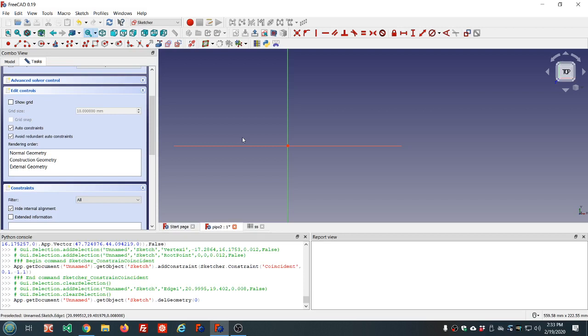One example might be the position of an endpoint of a line and the length of that line. If you got both ends of the line constrained with coincident constraints, then the line length might in many cases be a redundant constraint. So this avoids those automatic constraints that would be redundant.